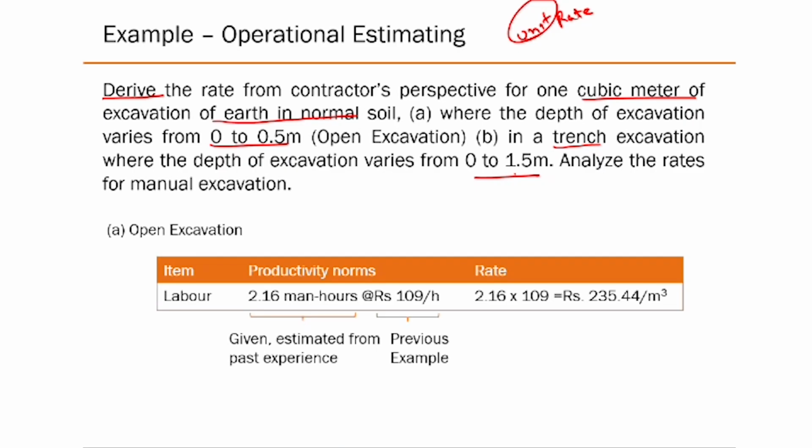What else? Do you know what's the difference between open excavation and trench excavation? Open excavation is slightly less deep, and the ratio of this, whatever this A by D ratio, is not too slender essentially. So there is not much risk of soil caving in, or there is slightly less risk of soil cave-in.